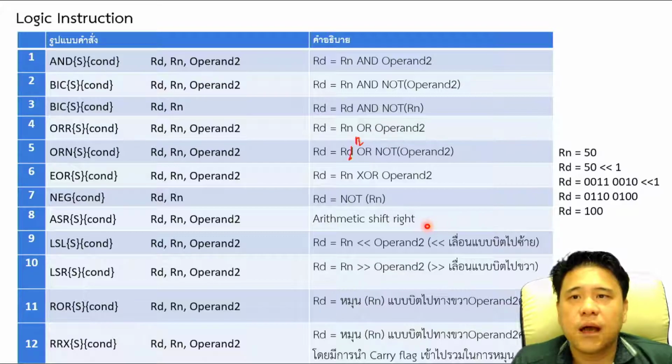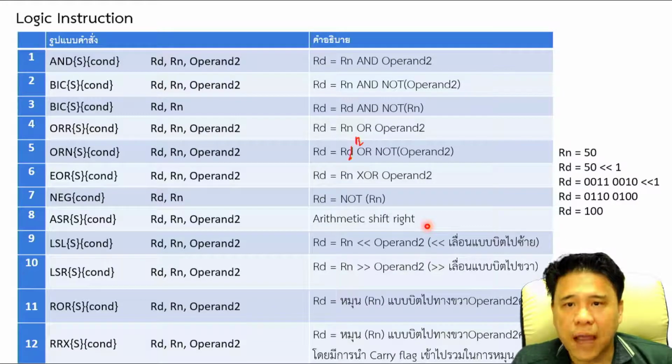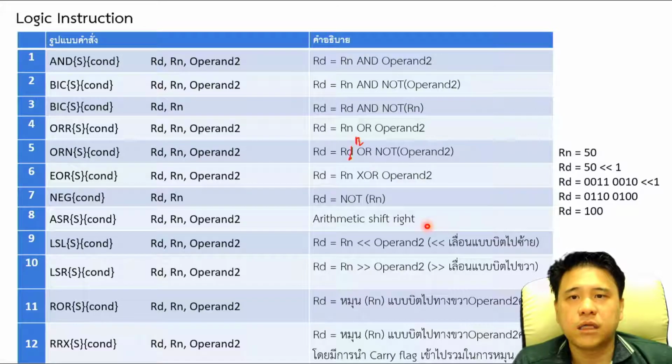In this case, sometimes we have negative numbers, right? A negative number is actually not a real number in the fixed point or digital environment, because digital doesn't have any negative numbers. We just use the most significant bit as the sign bit that shows whether this is negative or positive. Therefore, this bit should not be altered, right? Because this is arithmetic. Arithmetic means that we have positive and negative. Therefore, they will shift everything else rather than this bit and try to keep the information of the negative number after we do some shift operations. For the next slide, we will find the examples.